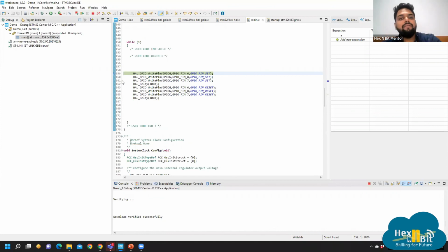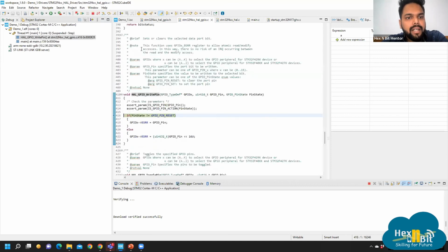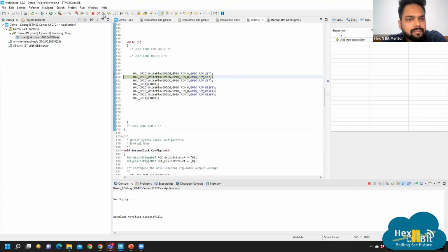Okay, now if I have to debug from the very core, like from the very core steps, I want to check at the register level what is going on in the code. So step into functions will go inside this function and will let you know where the code is, how the code is moving. First it is going in this mode. Then again, you can move out of the function. It will go to the next step. Okay, so this is step into and this is step over.